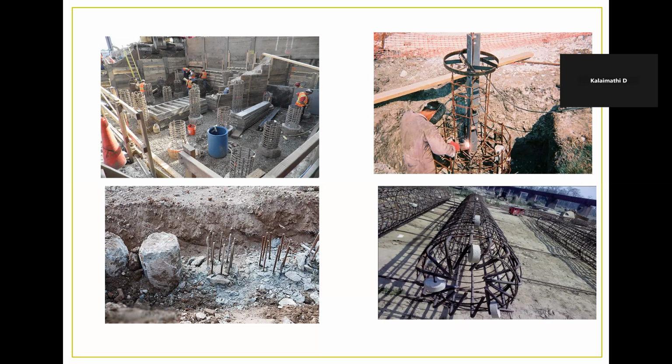The design shall be done based on those parameters provided in the soil investigation report, and those shall be verified after the construction by doing necessary tests.